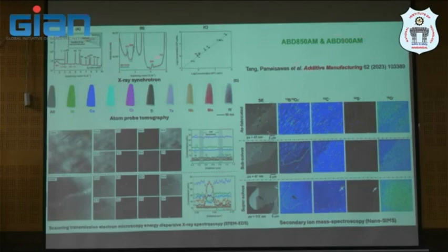alloys. And then you will see that there is no gamma prime peak detected by a high-energy light source like the synchrotron at all. And it's a printed solid solution. Actually you will see here, it's a perfect solid solution material after printing. And atom probe also shows there is some segregation, but it's not actually heavy segregation.